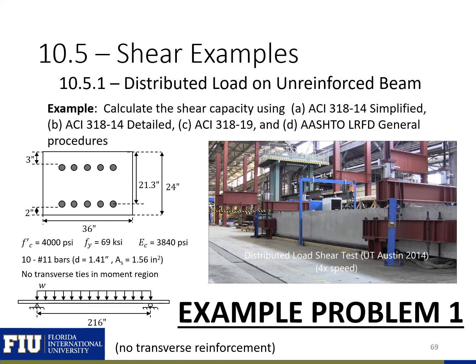So I'm going to play the failure video now from testing. You can see here the test setup is inverted from what you see on the screen. We have a distributed load being applied with an airbag on the bottom, and we have our supports on the top right here and right here. You can see already the flexure cracks developing along the length of the beam, and we'll see a shear crack develop right here on the right side of the beam.